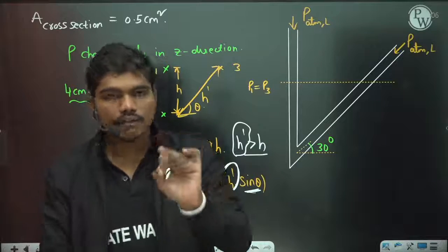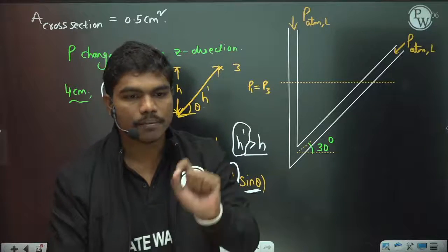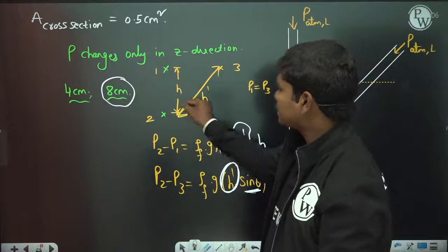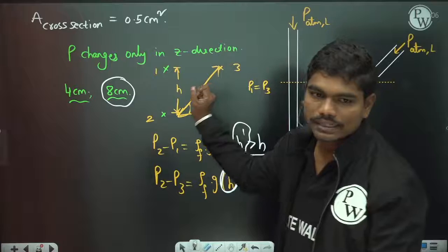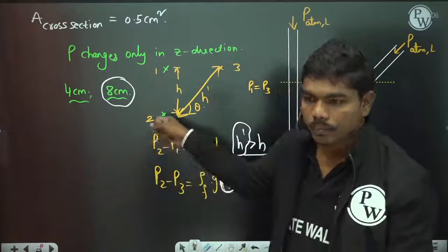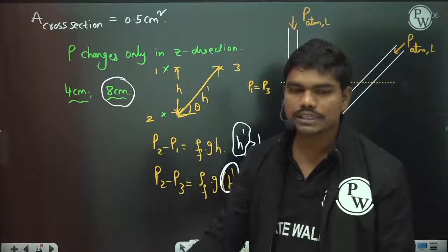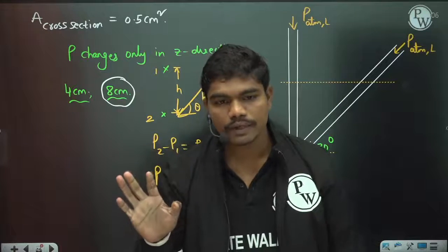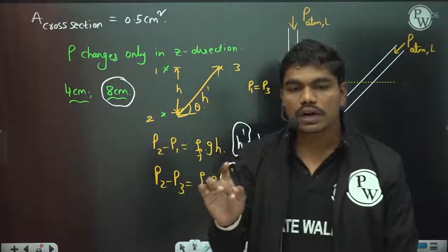Did you all understand how the inclined tube manometers came into existence? Because these manometers are more sensitive, and if you apply a small pressure difference, the deflection is comparatively more. So that's how your inclined tube manometers will give you readings with much better accuracy and, of course, with higher sensitivity. Is this clear to all of you? Did you all understand this clearly?